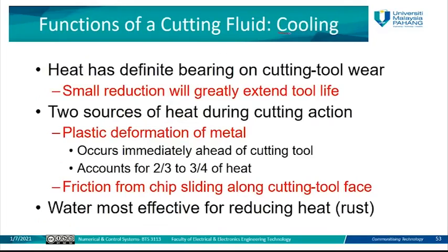For the cooling part here, heat has a definite bearing on the cutting tool wear, so a small reduction will greatly extend the tool life. This is what the cooling will do with the CNC tooling. It will increase their life because it will reduce the heat or temperature that will be produced.